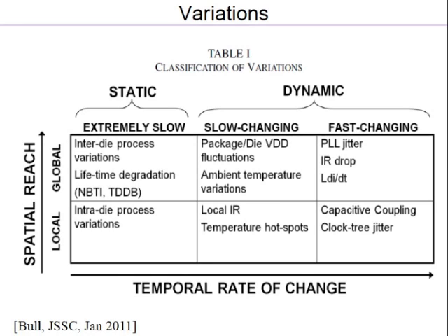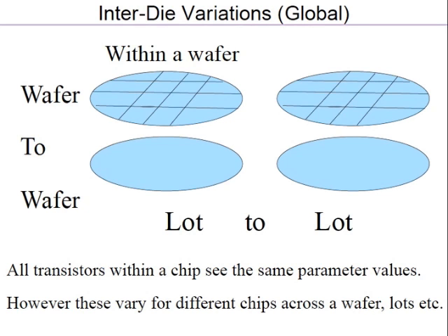It's still done in some cases, but the problem is you end up putting in so much margin that you can end up designing a chip which is not very competitive. Maybe you didn't need to put that much margin. If you had more visibility on these mechanisms, you could do something smart. So that has been basically the mantra which has emerged over the last 4-5 years, to try to have smarter designs which can reduce the amount of margining you put in your designs.